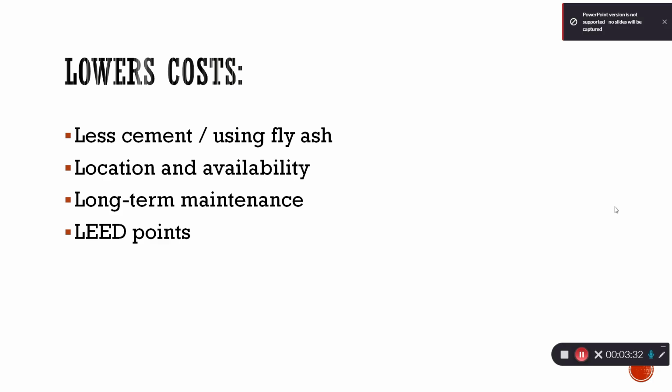The location and availability of fly ash has an impact on costs. It does depend on where the fly ash is located, how available it is, and other factors that affect the construction industry market on the price point of fly ash in a concrete mixture. If there is an increased demand for fly ash, the supply and prices can fluctuate as well. Contacting local suppliers and ready-mix plants can be a good place to start to discuss needs, availability, and pricing of fly ash.